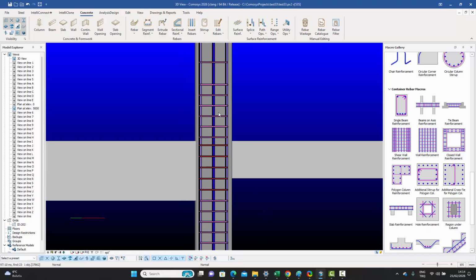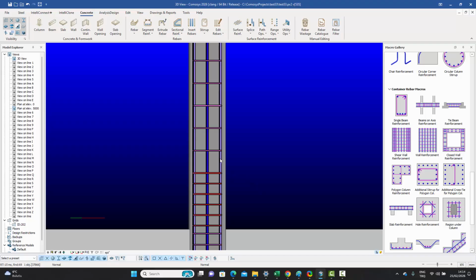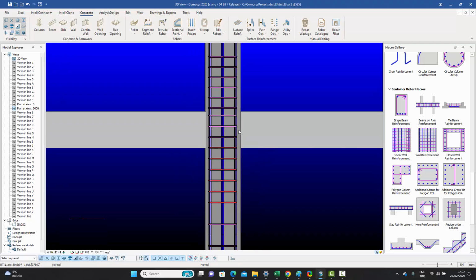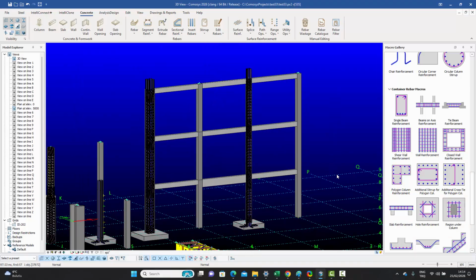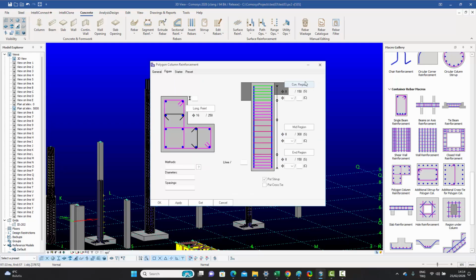I can have some control over that. Then I've got, so it recognizes where the second floor starts because of the beam connection. It's already put the second stirrup over there, the midsection, then the top one, and then this one, and so on and so forth. And if you remember, if you go back into the macro settings, we had these distances over here. So we had this one, and then this one, and then this one, and then this one, these 4 areas we could specify.